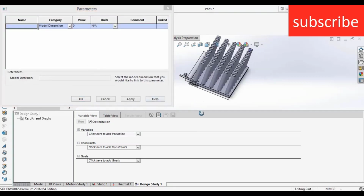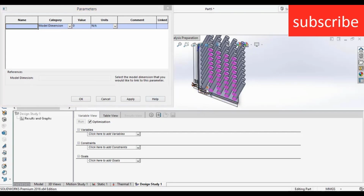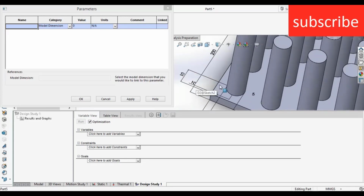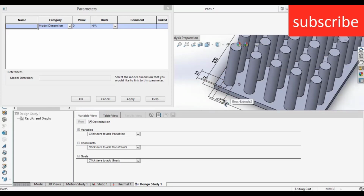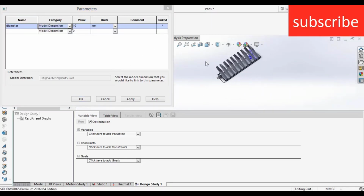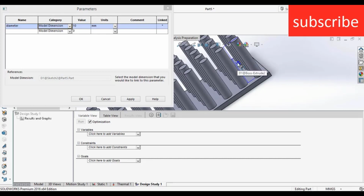After that, when you see this box, go down below and select the diameter. As you see, I selected the diameter, and you will see the value. Make sure you type the name of whatever you select so that it is easy for you. Here, diameter. Now the second thing I want to select is the height. So search for the height dimension. Here is the height, 50 mm.